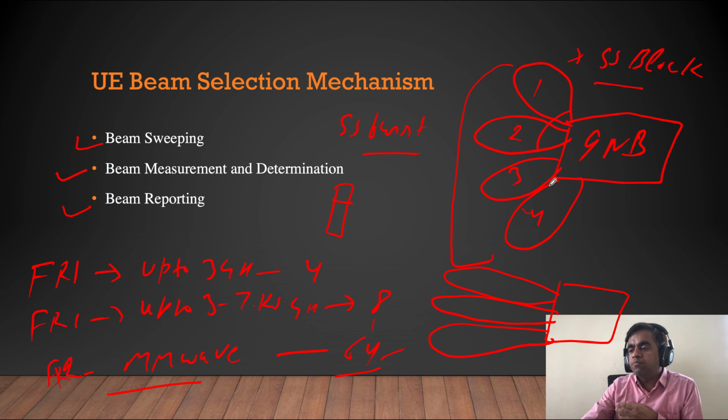So whenever the UE synchronizes, be it in idle mode or connected mode, depending on where the UE is, it measures the beam strength by the received signal. In idle mode, it is a synchronization signal, so it measures that strength. But if it is in connected mode, it is based on the CSI, the channel state information for the uplink and downlink. So the UE searches for the best beam periodically using some predefined thresholds, which are set by the gNodeB.